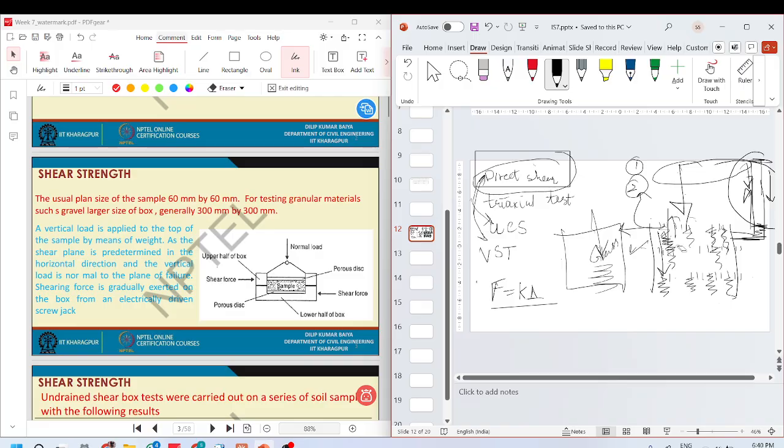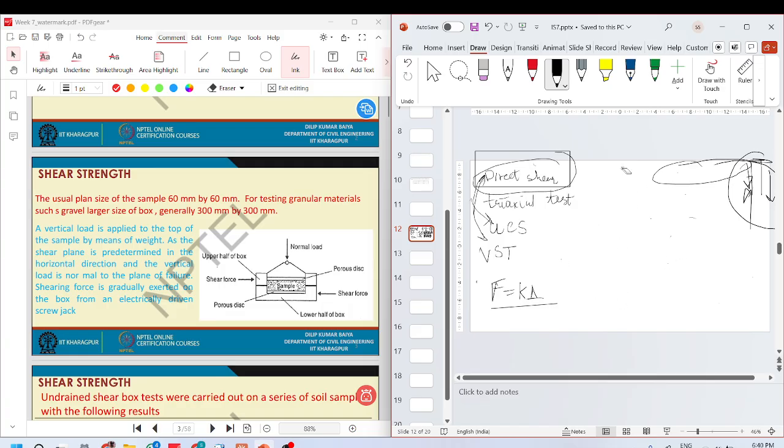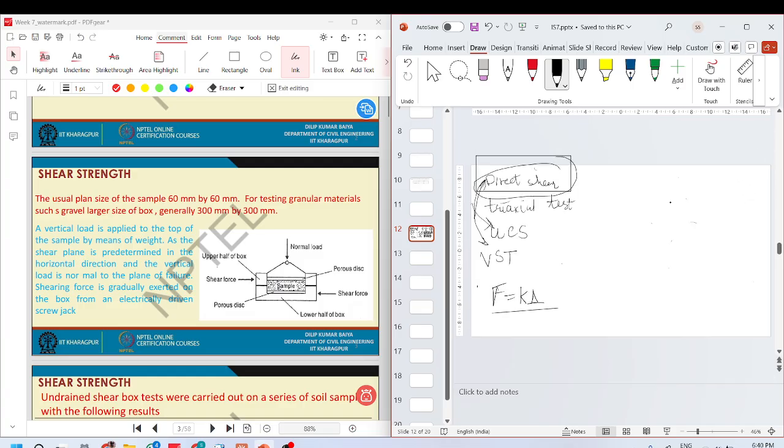So if you load a low permeability sample in a direct shear test, when you're loading, all the load is getting carried by the water, and you don't have the mechanism in the direct shear test to calculate the excess pore water pressure. So you can't actually do justice with an undrained loading test in which you are not allowing the drainage to take place.